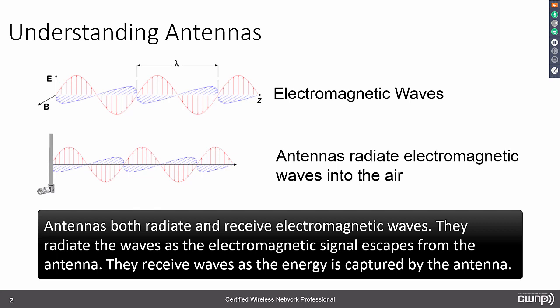And so the phrase might help you understand it a bit by knowing the parts of the acronym. Equivalent isotropically radiated power. The output power that we're getting in the intended direction of the antenna is compared to an isotropic radiator. So what is it in equivalence to an isotropic radiator, hence equivalent isotropically radiated power? And of course, we measure antennas in a very specific metric called dBi that we'll talk about a little bit later on.